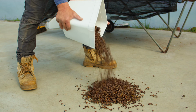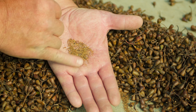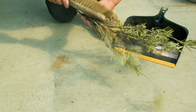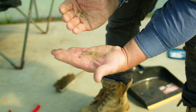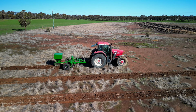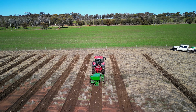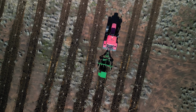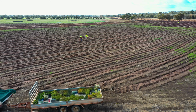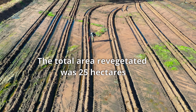Because we were afforded 12 months lead time in preparation to the actual restoration, it gave us time to go and collect Indigenous species local to that area that were going to be adapted to this site. So we've had around 50 species in this mix. The bulk of the seed mix was understory species and shrubs put through in the direct seeding mechanism, and the tree component was actually planted as tube stock. They were grown by the local Katanning nursery using seed collected that 12 months prior from local provenance.